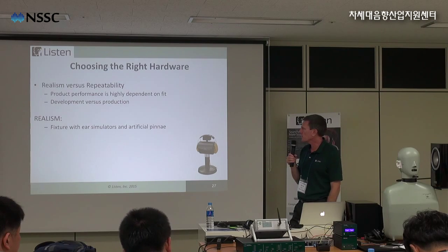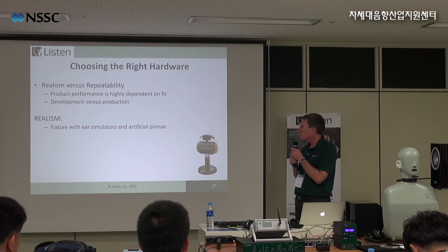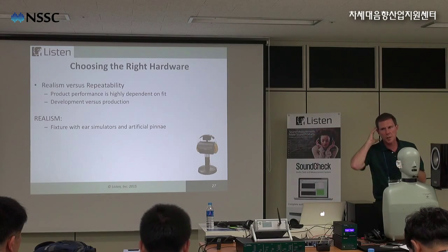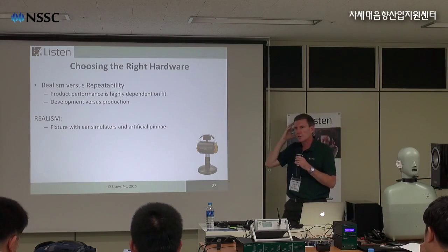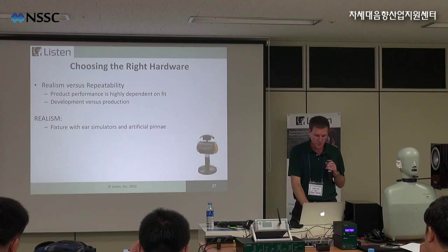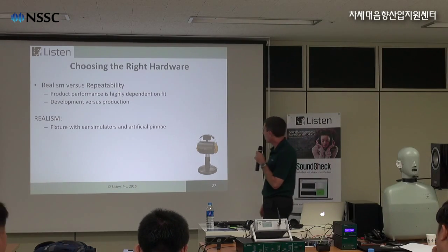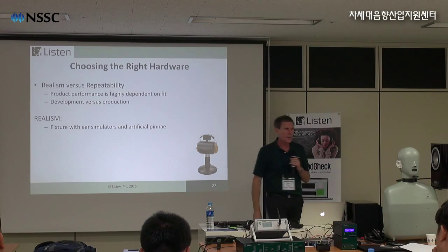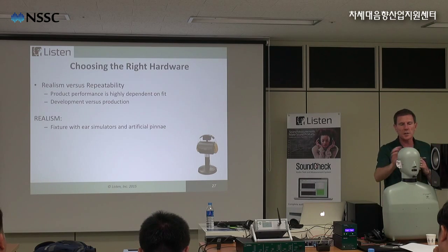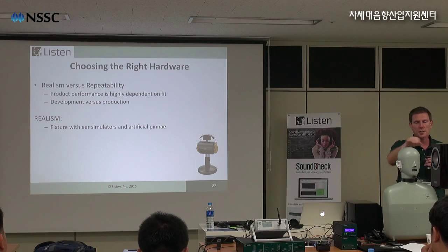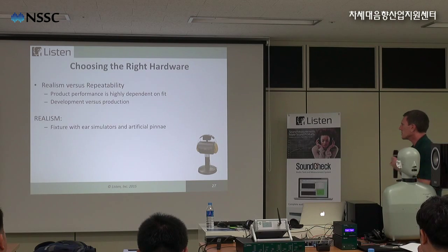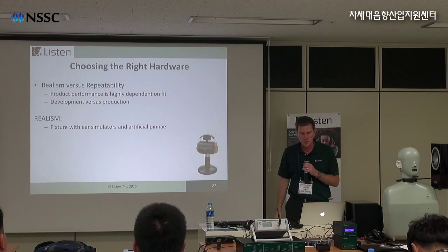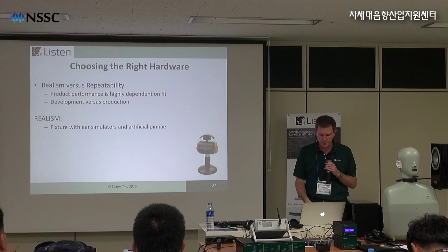So if you want something realistic, you have a choice. You basically need a pinna, because that's going to make a big difference to how the product fits and seals at low frequencies. There's one of them, and there's a simplified one, which I jokingly call a blockhead. You can't see it here, but it has exactly the same couplers as this guy does, and two pinnas, but it doesn't have a mouth or all the fancy stuff. It's just for measuring headphones or noise cancellation headphones.